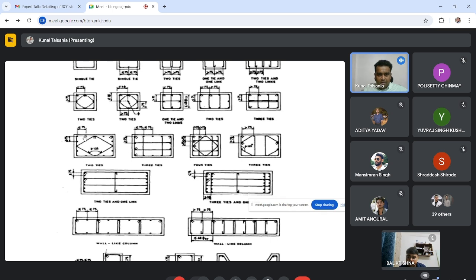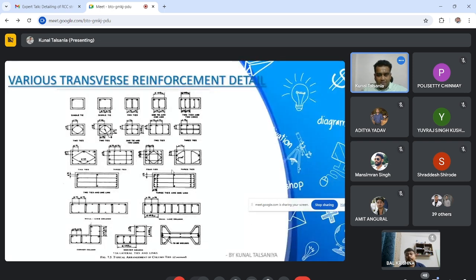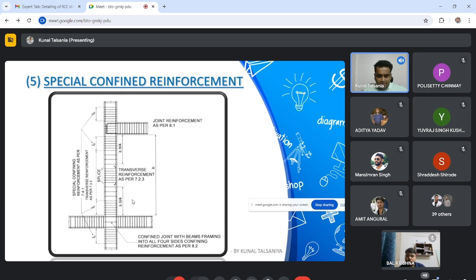See, why have they not given stirrups here, or here, or here? I will explain. Because the spacing between two bars they have kept is less than 75 mm. That's why there is no need to restrain this bar. They have to follow that at every 150 mm your bar has to be restrained. That's why they have provided detailing like this. Okay, this I have explained.